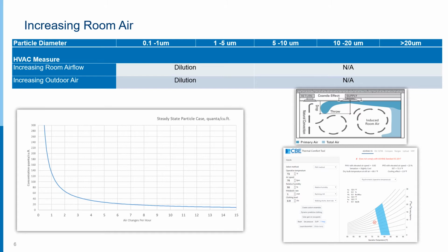When we talk about larger particles or droplets, the room ventilation itself is not going to do much of anything. We are not going to pick up those large particles and move them. At least we're not going to do it on purpose, because we just don't have anywhere near the capture velocity that we talked about 2 slides ago. So we may get some large particles up in the ducts by accident, or if they get directly coughed or sneezed up there, but our room ventilation is not really a meaningful tool to affect larger particles. Smaller particles, yeah, fine, but not larger particles.